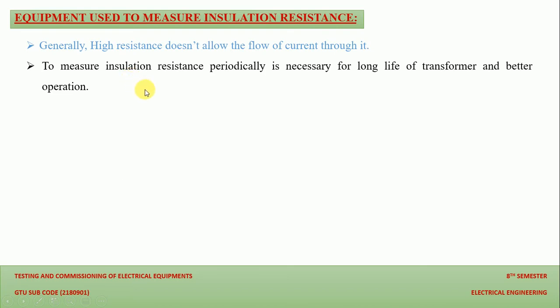at that time also we perform this test to check the insulation resistance of the winding. That will be useful to check whether any short circuit has happened. If the insulation resistance is not proper, then we cannot use that device for our operation purposes.